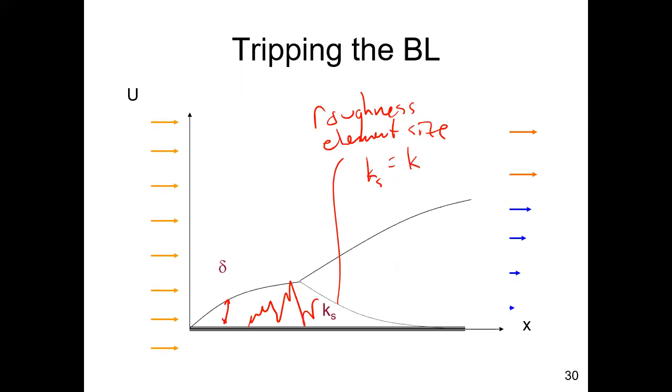And when we want to artificially roughen the surface, basically what we're trying to do is avoid any laminar characteristics from the leading edge on. And so what happens is if you create turbulence at the beginning of the flat plate, it's turbulent for the rest. The laminar sublayer or any laminar boundary layer cannot reestablish once you have the turbulence.